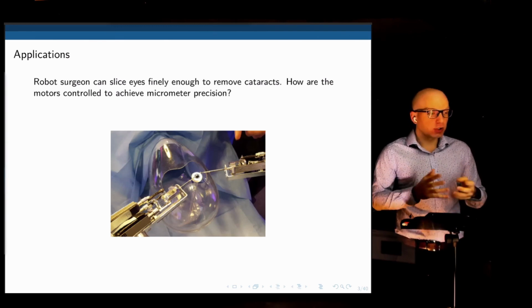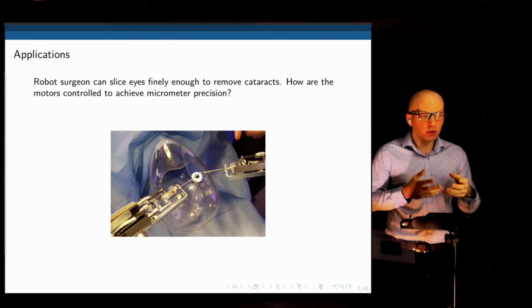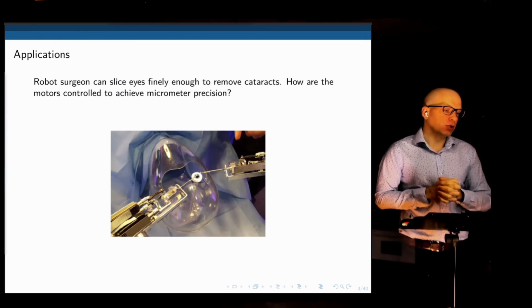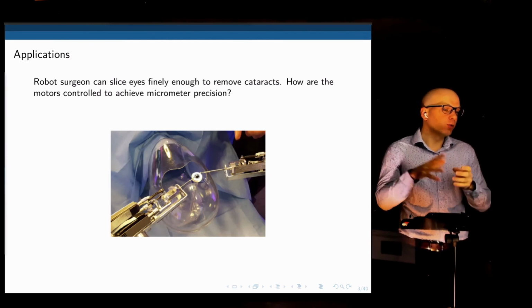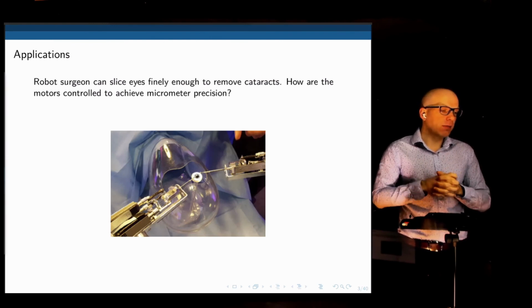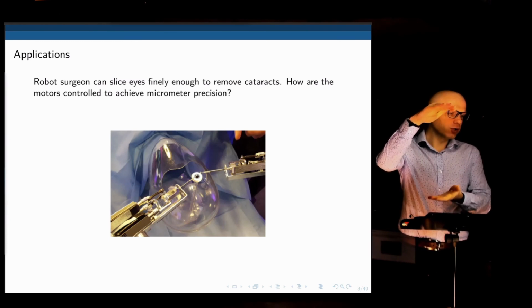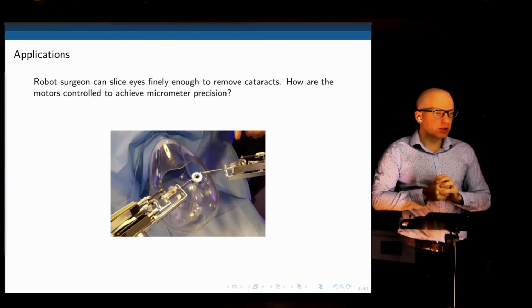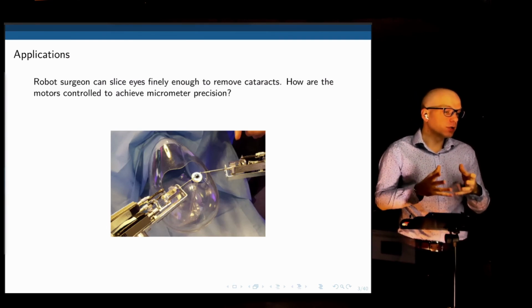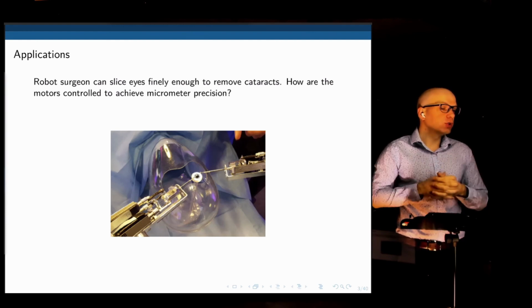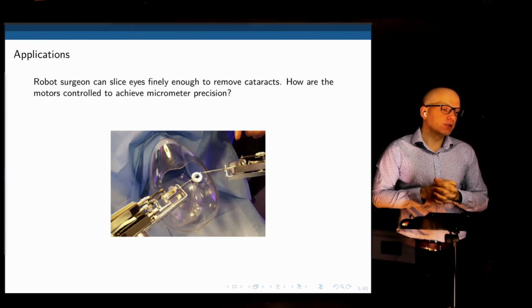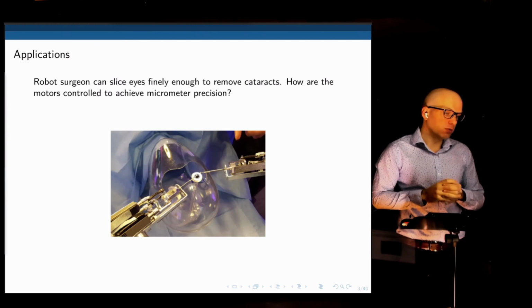Another great question that we could ask here is how can we control these motors to achieve a precision that is in the micrometer range? I'll give you an example. I have two robotic arms in my lab. They are pretty much this tall. They look like toys, but they are industrial robotic arms, and they have an accuracy of 5 micrometers. It's micrometers. It's really precise. How can you control these motors one by one, combine 6 of them, and they still have an accuracy of 6 micrometers? Well, this relies on a perfect closed loop control for position or speed control.